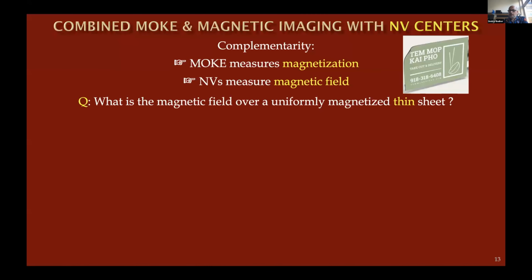And what you will find, maybe to your surprise, maybe not, is that these things are actually something that's called a Halbach array. This is actually a periodically poled magnetized structure. The period is maybe a millimeter or so, and it's up, down, up, down, up, down.